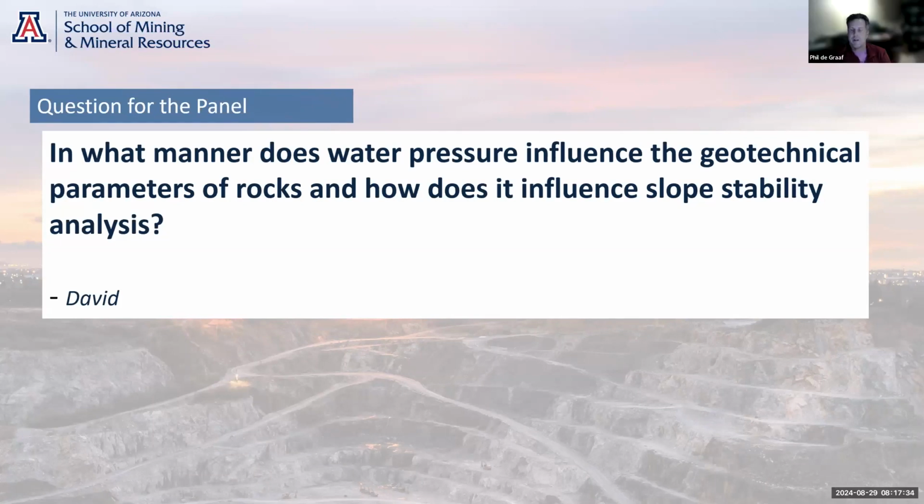Sure, Gillian, I'll add to that a little bit. I suppose the other element is the time factor, in that very seldom are groundwater conditions static. So the one end member is the transient pore pressure changes due to rainfall or freshets, snow melts, and that type of thing, with a high peak of pore pressure that dissipates quite readily.